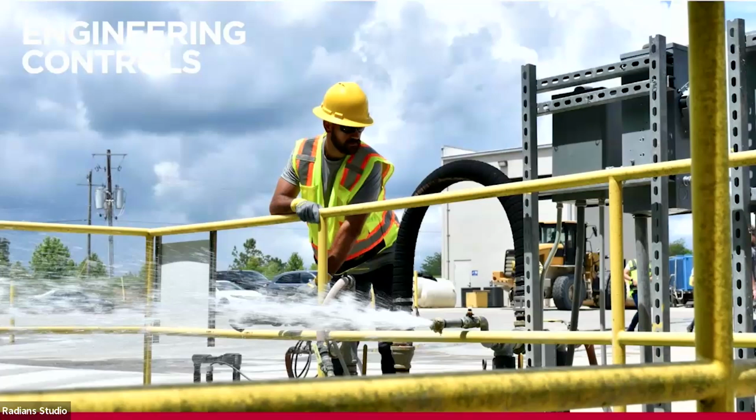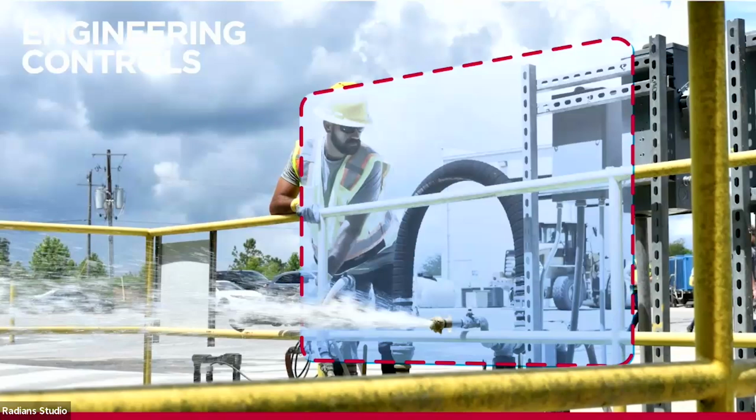So how would we look at this situation? We look at it and we say, okay, can we eliminate the hazard? No. Can we substitute? Well, there's really no substitution here. You're relieving a valve from something, okay? So can you engineer control? Absolutely, you can engineer it. So you could take a plexiglass shield, you could place it around that pipe to where the worker could stand behind that plexiglass, and now you've engineered controls so that that worker is now safe. So a pretty impressive way of doing that.